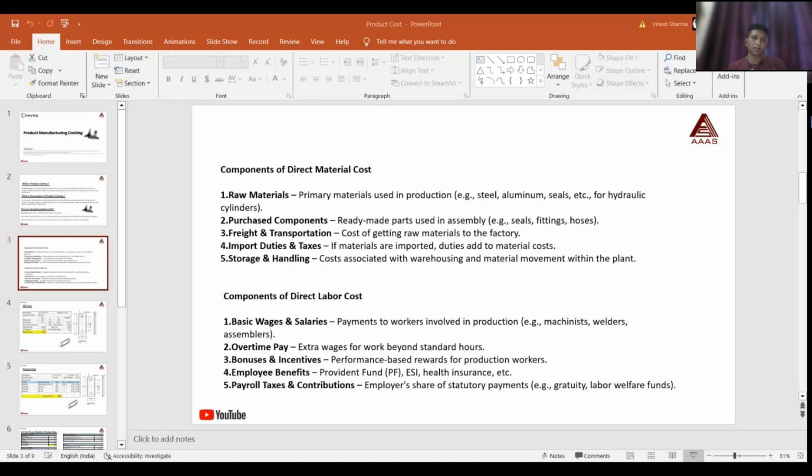How to calculate material cost. We move to how to calculate the RM cost. In this week, we take one sheet metal part. This is the drawing. If you understand, the part profile is one side of 100 mm. All dimensions are in mm. This is 40 mm, and this flange is 8 mm. So what will be the blank condition of that? So blank condition: 100 mm and 40 mm and 8, so 8 plus 8 is 16 plus 40, that is 56 mm.